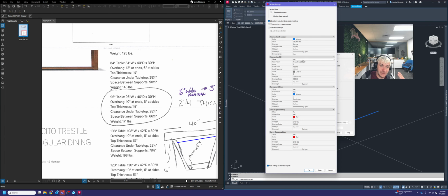Go down to the next one here, intersection fill. That's just a fancy term for hatching. So when you see intersection fill, just think that's my hatching there. So we do want to see the hatching. We're going to set this to, well, it's already set this way, predefined / solid, which means that it'll just make a solid hatch until you change it.